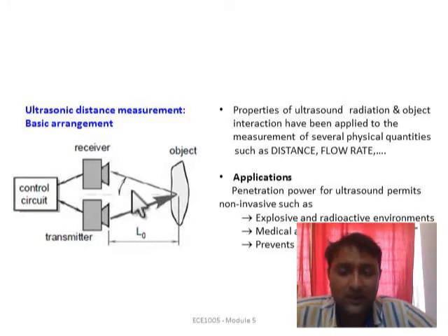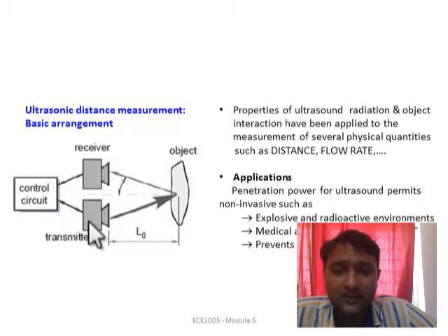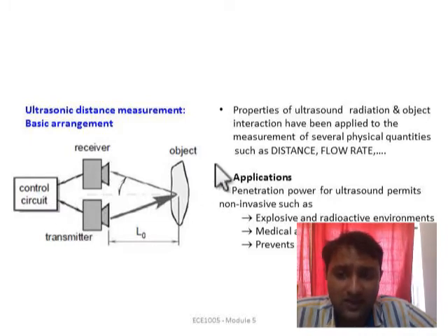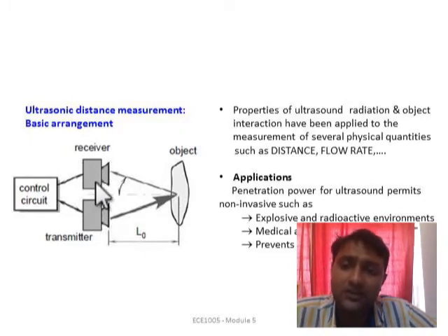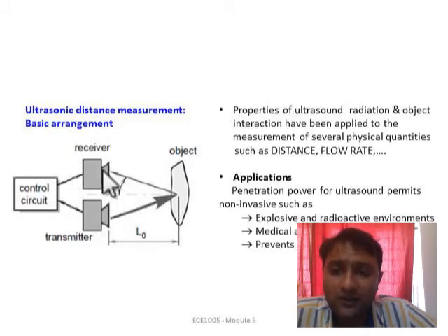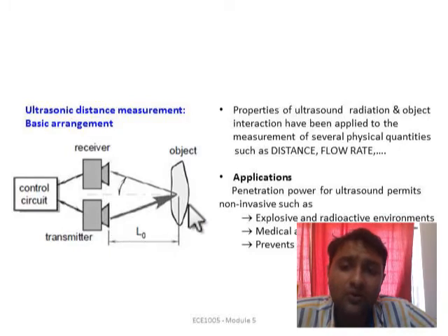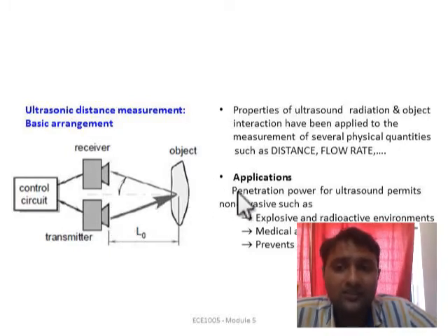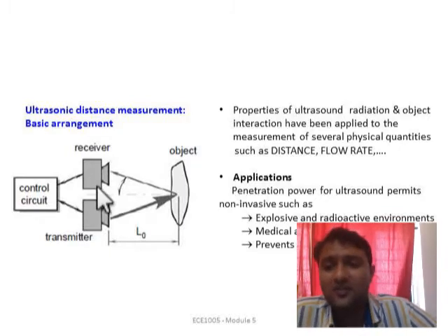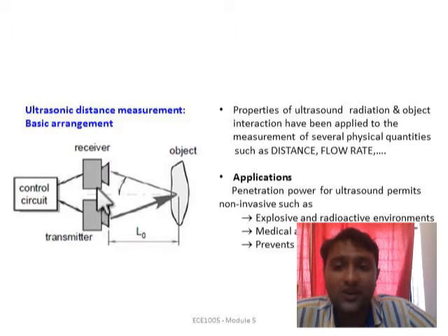So the distance is inversely proportional to the amount of current received on the receiver, in the intensity based measurement. And if you have applied a pulse at a time t1, and the pulse is received back again with a lesser intensity at time t2, the difference between time t1 and t2 gives you the direct measurement of the distance traveled by the pulse. The larger the distance traveled by the pulse, the greater the reception time, which is similar to something which happens in the echoing effect.